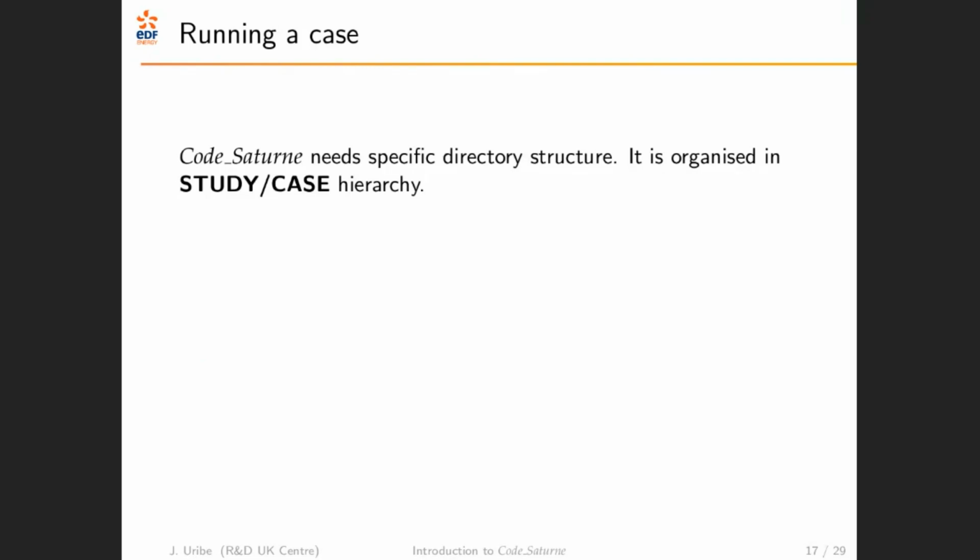In terms of how to run a case, it's a bit different from other software. Saturne expects to find by default a specific folder structure where it organizes all the input files and the user subroutines. The easiest way to do this is to use the Code Saturne command to create this structure.